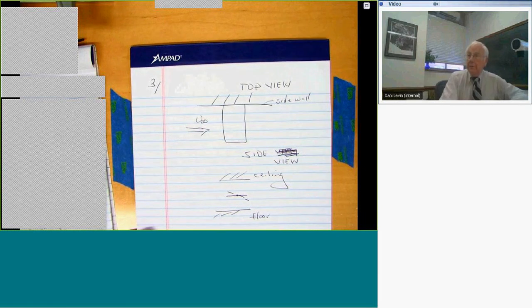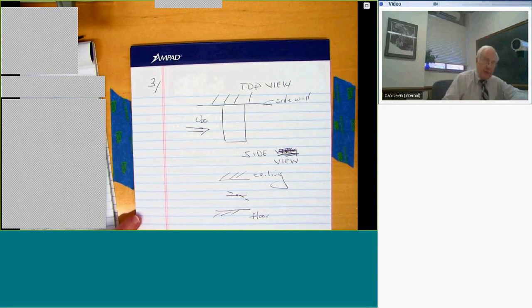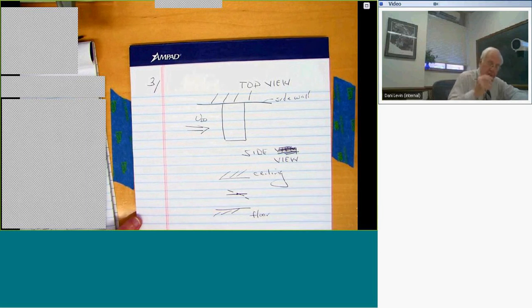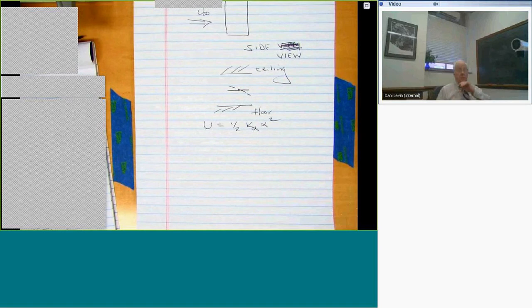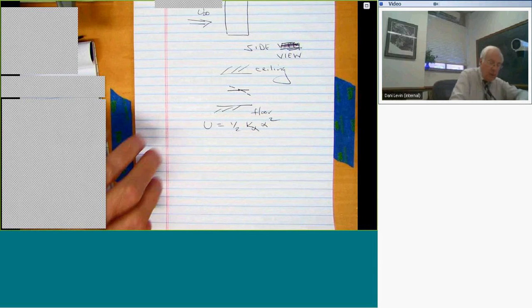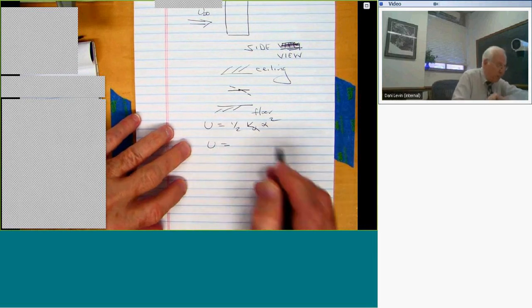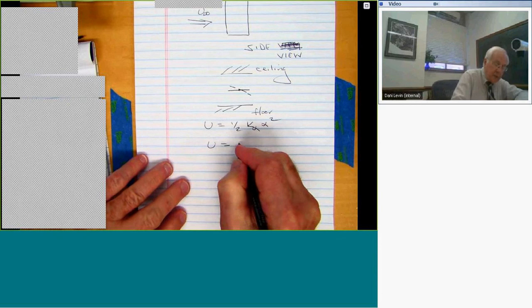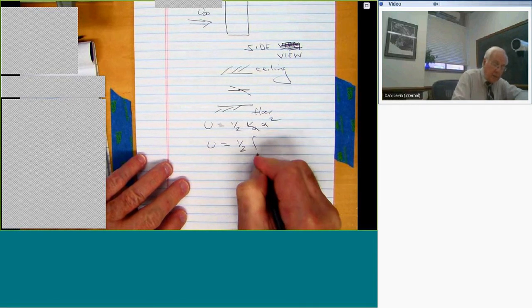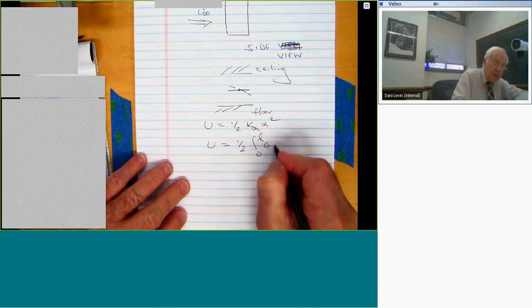But we can do better than that. We certainly want to do better than that when we're really doing it for pay, right? For some fine aerospace organization. And the way we do better is the following. Rather than using this representation of the spring to model the elasticity, we use what is sometimes called a torsional rod representation, where we have 1/2 now the integral from 0 to L of GJ.